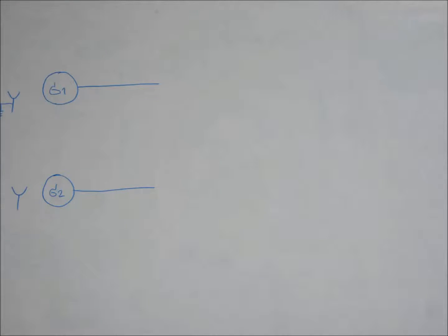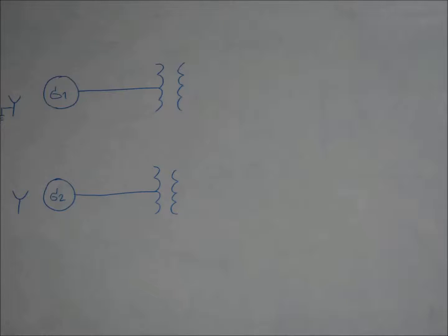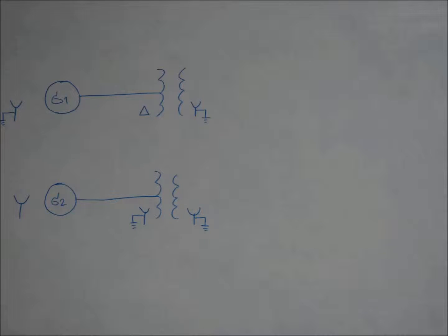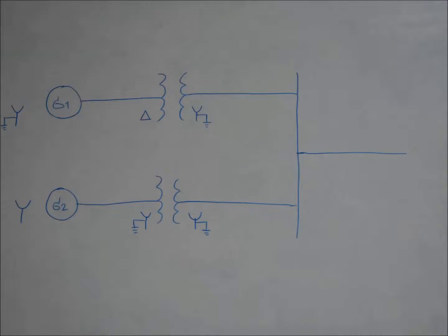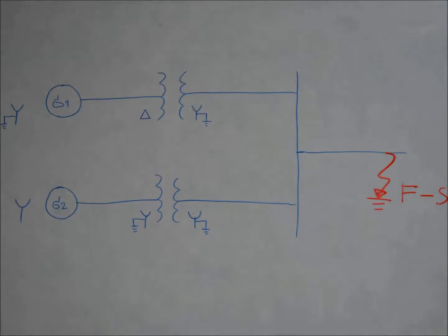Two generators, generator 1 and generator 2, are connected respectively through transformers T1 and T2 to a high voltage bus which supplies a transmission line. The line is open at the far end, at which point F a fault occurs. The pre-fault voltage at point F is 515 kV.